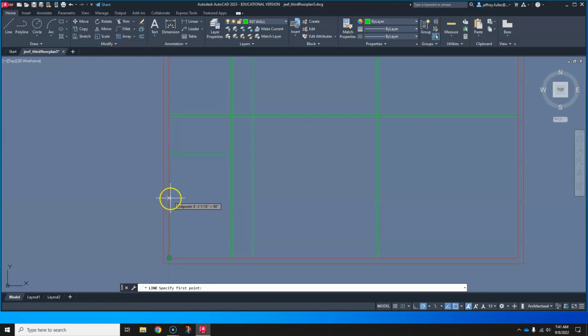But that's what's happening. Okay, and at this point, I can type a distance, or I can just drag the cursor until I get a distance that I like, and then just draw all the way across. And I think I'm going to take this line all the way across here. And then I want to do an offset and do it 4.5 inches for the thickness of the wall. Okay, right there. All right, so I've got some room space down here, pretty good room.